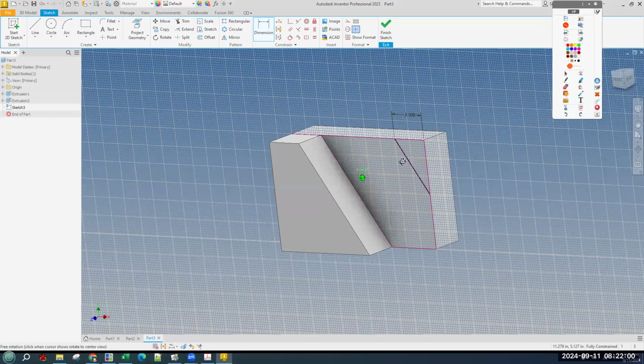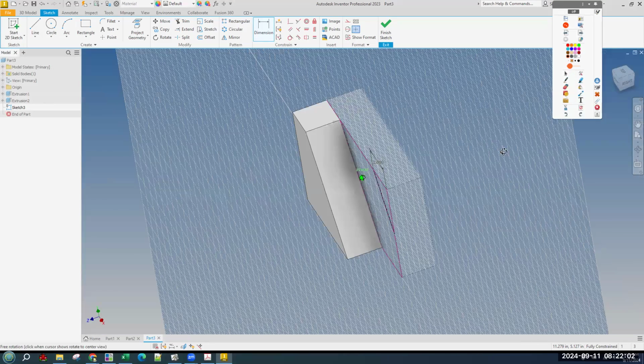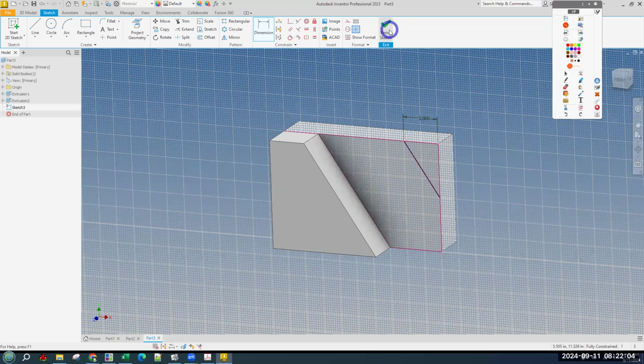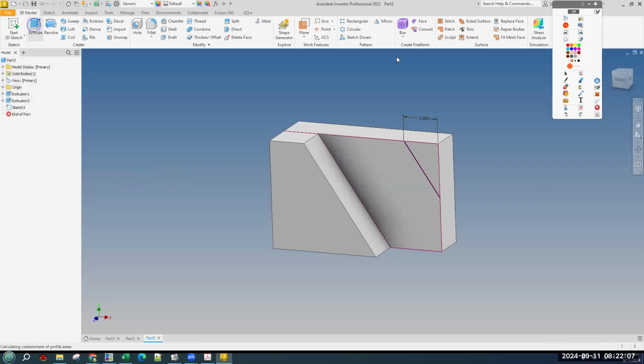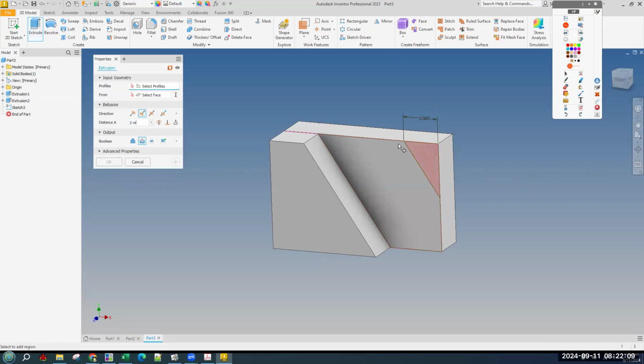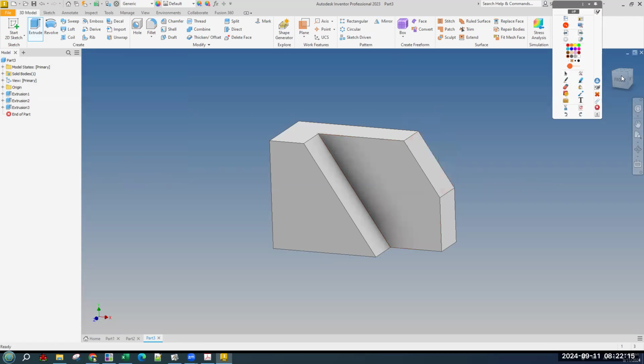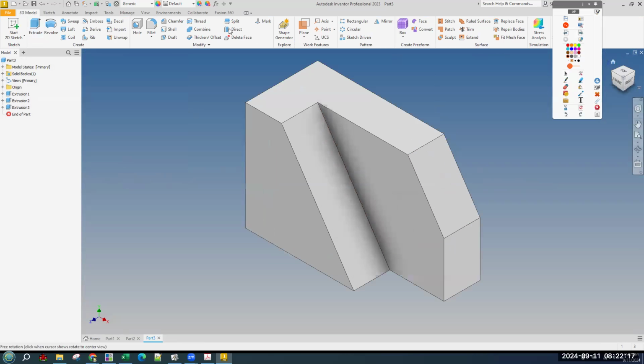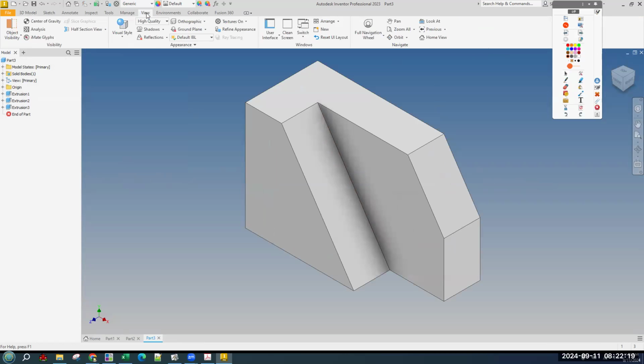Okay, and you can see where we are sketching, what the shape actually is. Let's finish sketch and extrude. Choose our triangle, switch it to cut, through all just because, and hit OK. And there you go. And we'll view.